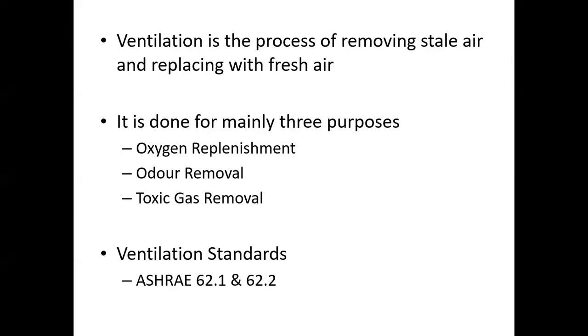Down the line, once you have got the entire FACFM values, you need to add up the values, which means the individual ones that we have done now. For example, manager cabin 60 FACFM, chairman cabin 100 FACFM. You need to add up all those values, and you will end up with a bulk value like 3000 FACFM. So that is the capacity of the fresh air machine.